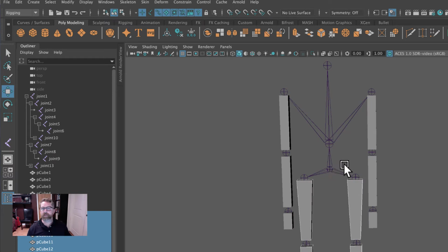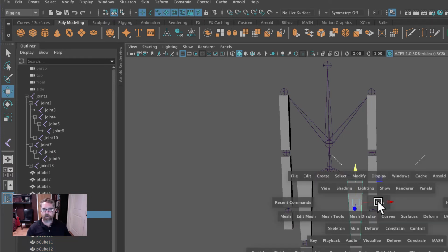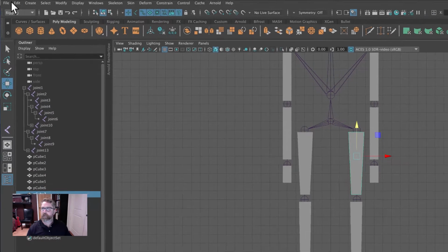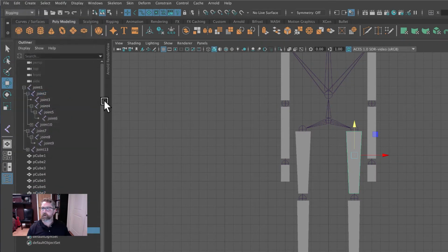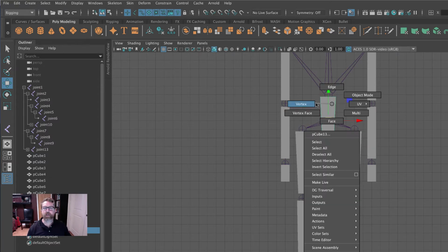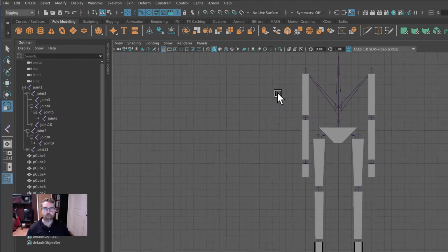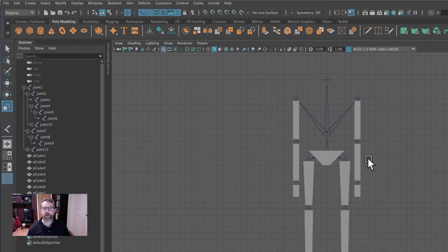All right, and then let's just create real basic. We want 3 pieces here. And we could just start from this leg, maybe easier to do in the front view. We'll duplicate that. I'll come the long way. Shortcut is Command D. We'll grid snap this up into the middle. We still have joints masked off, so easy enough for us to kind of pull this down. And this will be our pelvis shape, something like that, just a stand-in. Again, you can, once you're done animating, import some better geometry.